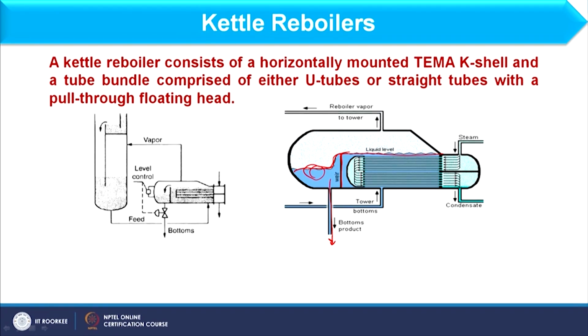And as far as design of reboilers is concerned, we will discuss each and every detail of whatever I am sharing right now, okay. What is the tube bundle diameter, what is the height of the weir, the number of tubes, etc., and what is the space I am providing as vapor-liquid separator, what is the area of that, right. So, in this way we complete the design of the reboiler, okay. But that is not a simple step, it includes different steps, okay. So, that we will discuss later on.